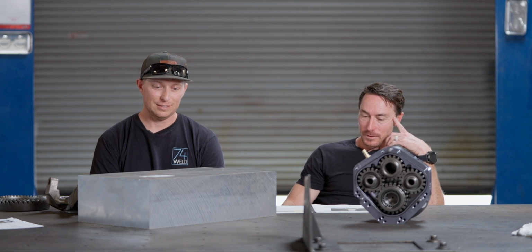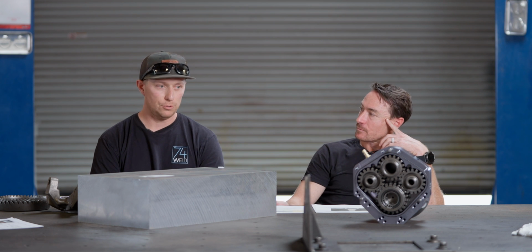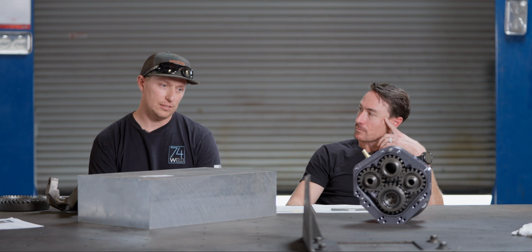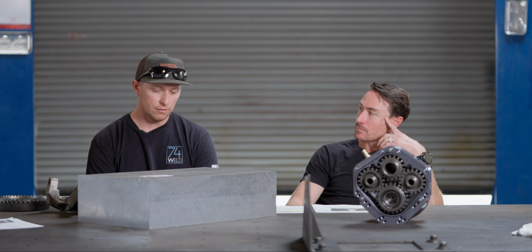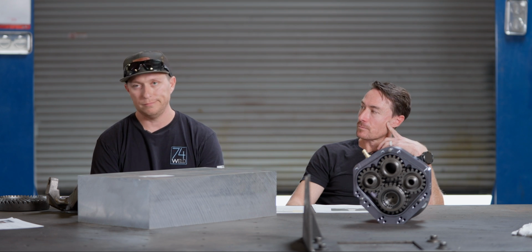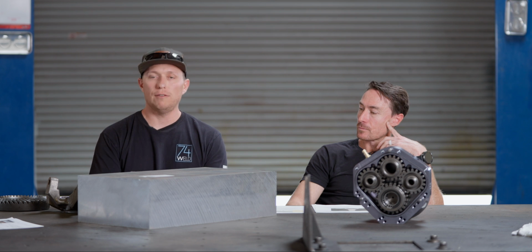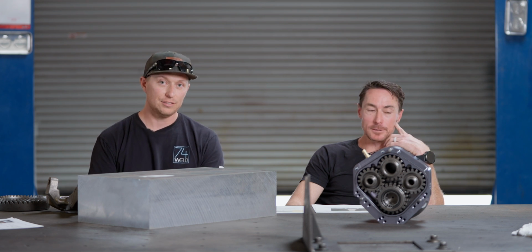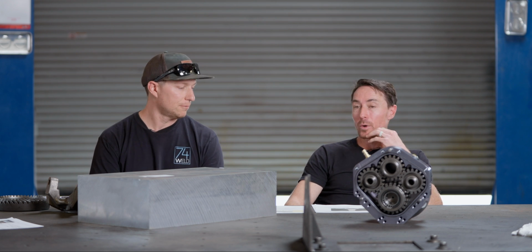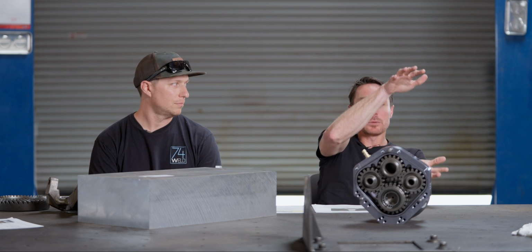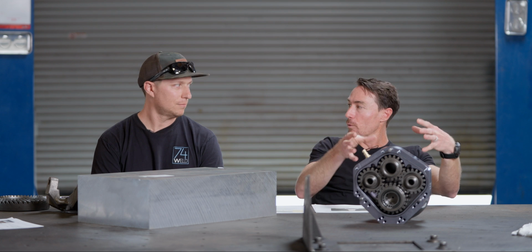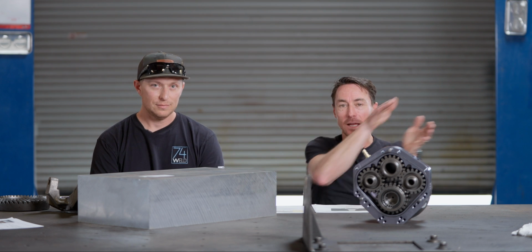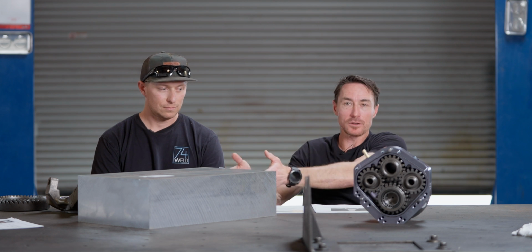Yeah. I mean, one note on just forging tools as well. Like if you look at casting tools, you can have one match plate that you use over and over and over again. It's essentially you have one tool that makes the part. For a forged part, you could need a series of progressive dies in order to get to that end stage. Oh, that's a good point. So it would go and be mushed into a general relative shape, and then it goes to the next die and mushed into a little different and goes to the next die. And so it progressively goes into the shape that you want.